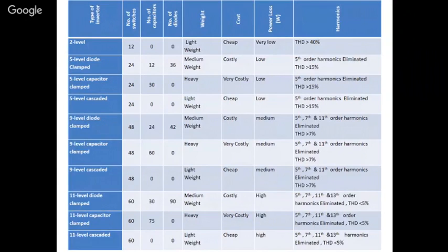What we feel is, instead of reducing the DC sources, whenever you go for a PV system, or maybe you want to connect wind, then reducing the number of sources is good. But for PV, what we mostly suggest is to have a number of sources, because PV comes as different modules, and partial shading and all these effects can be overcome. So for PV, this topology is the best.